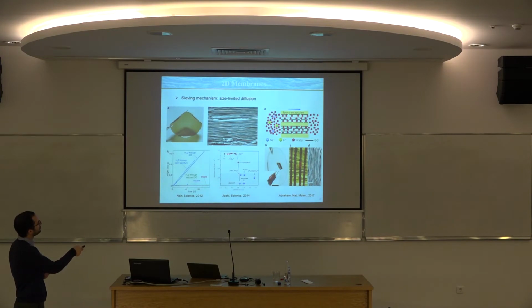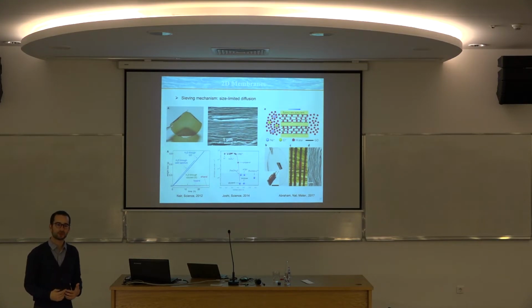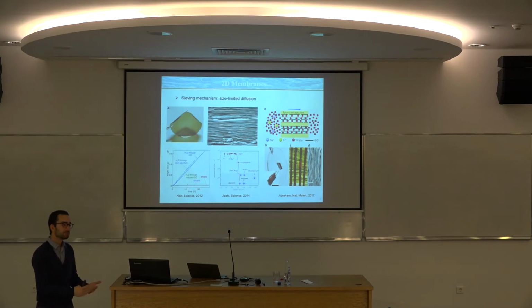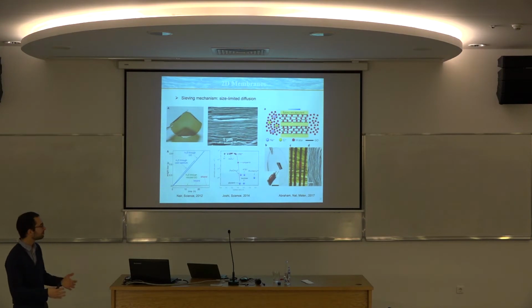You see the high permeation rates from the smallest molecules or ions, like potassium. Then when you increase to magnesium, propanol, sucrose, which are a lot bigger, you have a huge drop in the permeation rates. And the cutoff is, I think here, slightly higher than 4 angstrom. So anything larger than 4 angstrom could be blocked, okay? Which is good because in principle you can block hydrated sodium, so you can use this membrane for desalination.